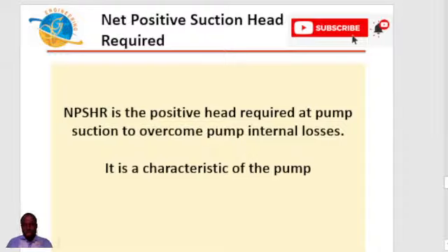No engineer wants to be responsible for installing a noisy or slow or damaged pump. You don't want to be responsible for that. So that is why it is very important, it is critical, to get what? The NPSHR value determined by test characteristics, which you obtain from the vendor.